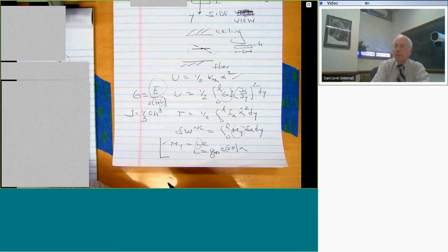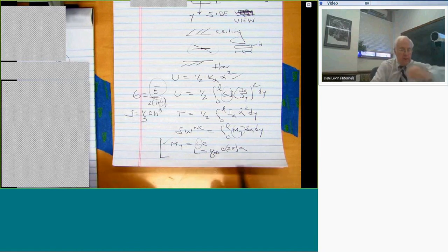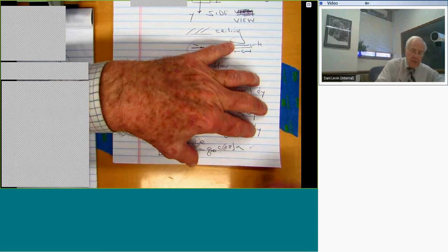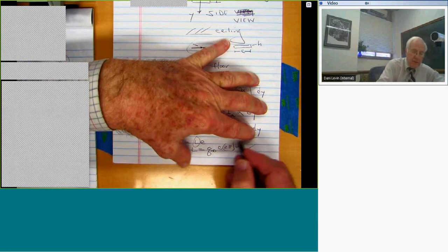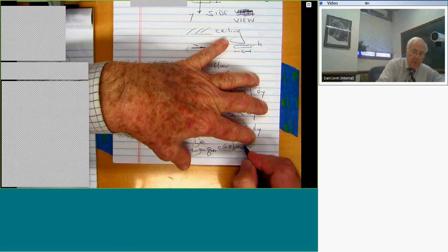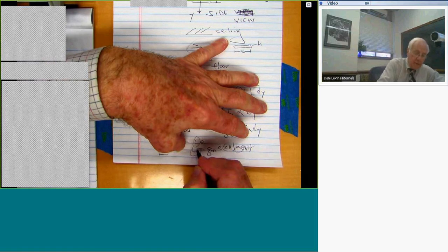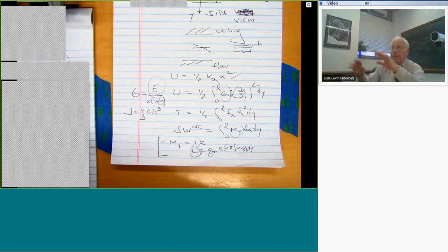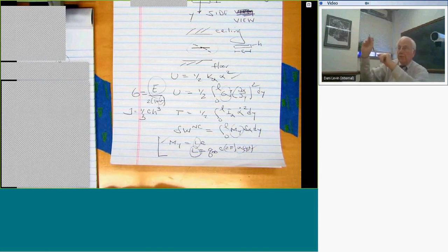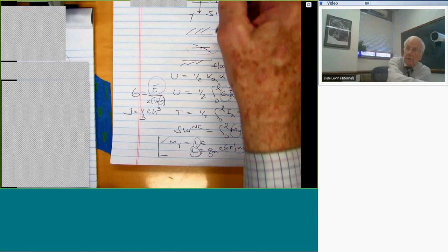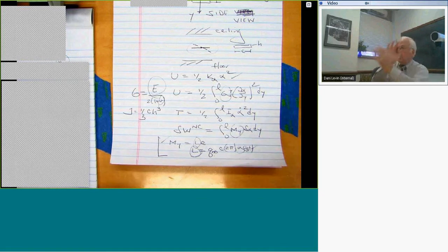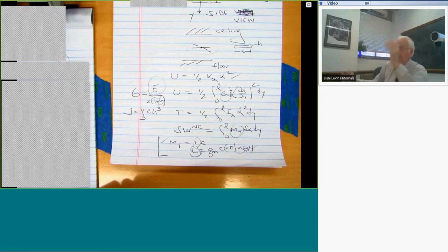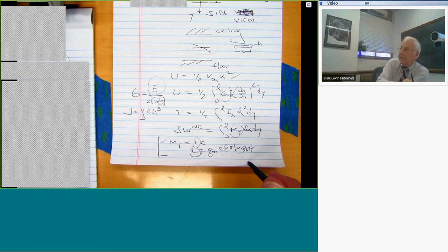The next level of improvement beyond this is to recognize the following. In this equation that relates lift to alpha, alpha, of course, may depend on y and t, and therefore, obviously, L does too. But in reality, the lift at some position y along the span depends on the twist at all other locations. It doesn't depend solely on the alpha at the same location at which I measured the lift.